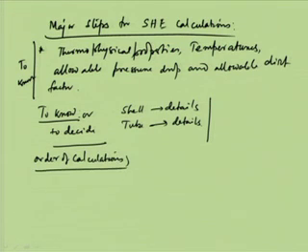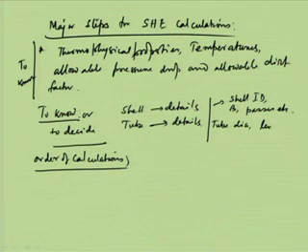Now, in the shell details and tube details, in shell details we can understand shell ID, baffle spacing B, then passes, etc. And in tube details, tube diameter, length, okay. Then we need to know the pitch, passes, etc. These things are to be known or to be decided, okay. And then the order of calculations, if we just see one by one.